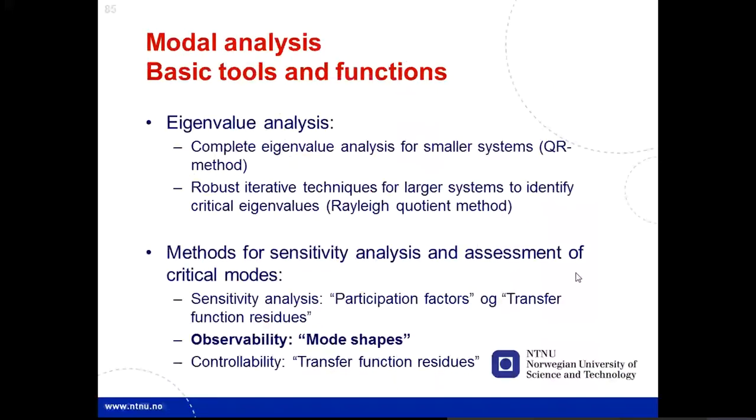I think we have discussed earlier that if we want to understand how the systems oscillate with respect to each other, then we are interested in determining the participation factor and the mode shape. I will not discuss transfer function residues because we have not discussed them earlier, but mode shape and the participation factor we have discussed, as a part of modal analysis.